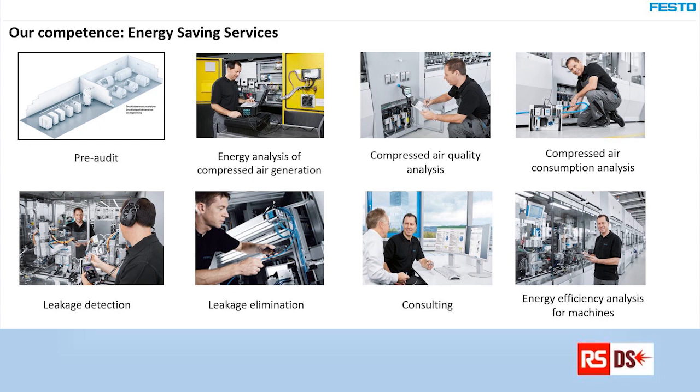During this audit, the complete system is analyzed, as I mentioned at the beginning, the holistic view on the system. And we do various measurements during this audit. The audit takes 1.5 to 2 days, depending on the size of the plant. First of all, we are checking the data of the compressors. Running times are determined. The compressed air quality is measured in several points. First, directly at the central preparation, in the compressor room, and then 2 or 3 times outside, somewhere in the production.